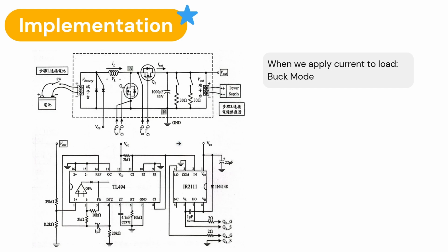The power stage consists of two synchronously controlled N-channel MOSFETs, QA and QB, connected around a common switching node A. QA operates as a low-side switch and primarily controls the inductor charging interval, whereas QB operates as the high-side synchronous switch responsible for energy transfer to the output side. During boost operation, QA stores energy in the inductor and QB releases the stored energy to the output capacitor. During buck operation, the energy flows in reverse and QB becomes the primary energy transfer switch.